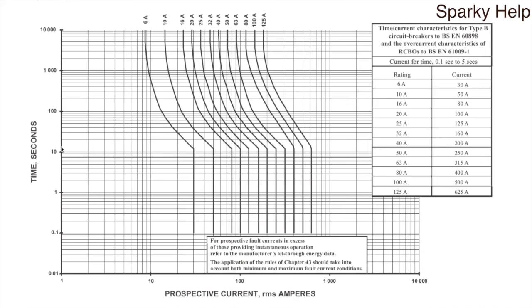So when they work, but you go even 1 amp under that threshold of the current in the table, they will disconnect really slowly in comparison. So 30 amps, they go in 0.1, 29 amps, all of them go over 10 seconds. So you're probably looking at 12, 13 seconds for those protective devices to go, which is not good because it means the cables now are overloaded for that period of time.